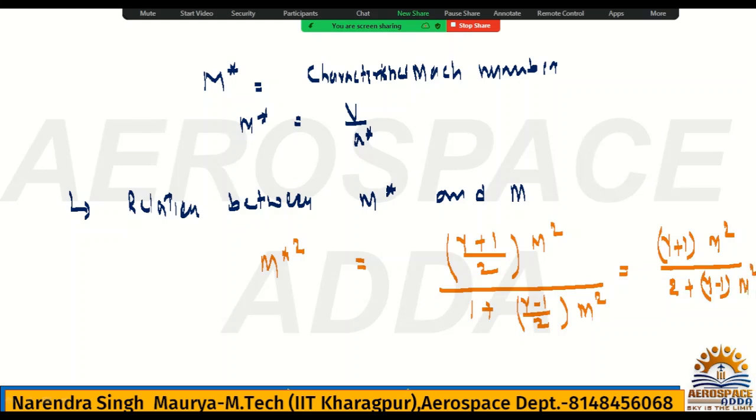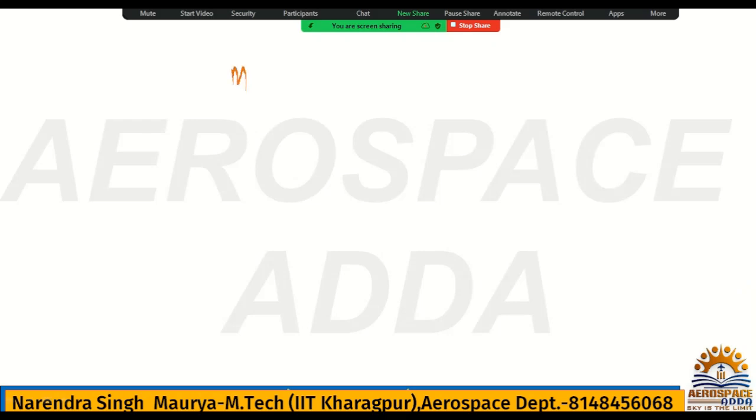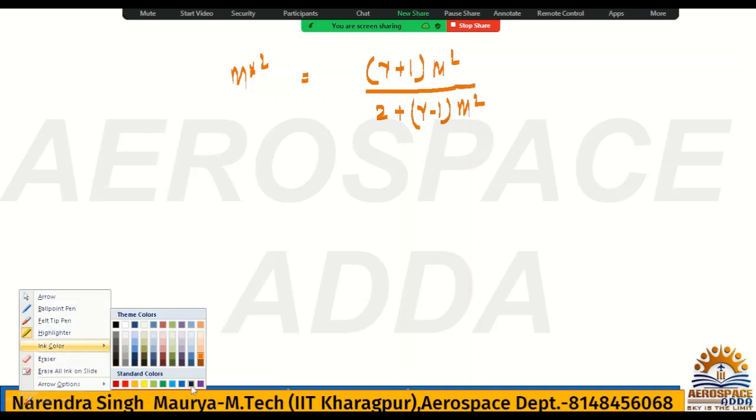Yes or no? So what is the M star square? It is gamma plus 1 M square divided by 2 plus gamma minus 1 M square. This value you need to remember, okay? It's very special.